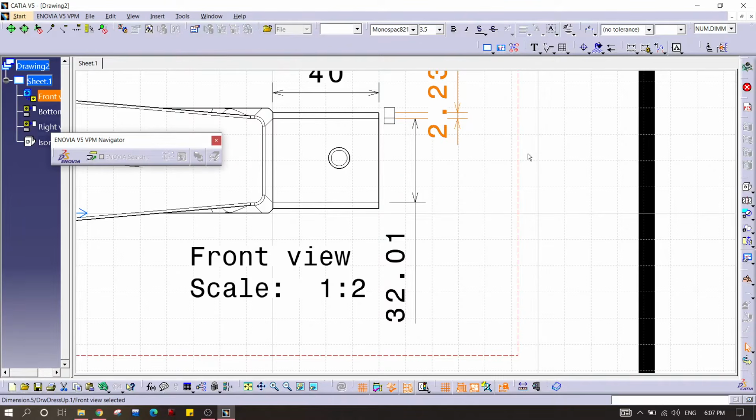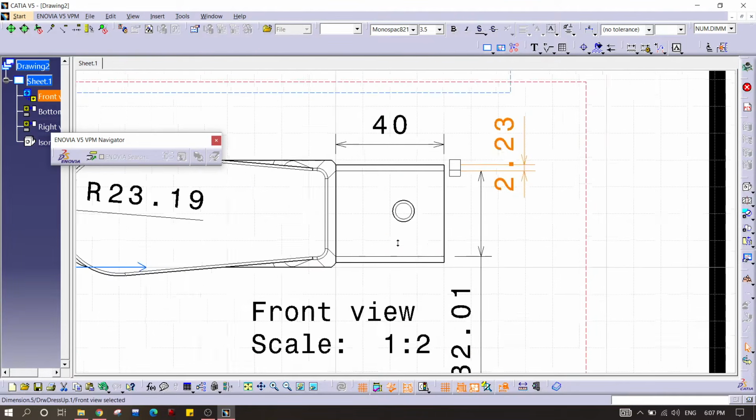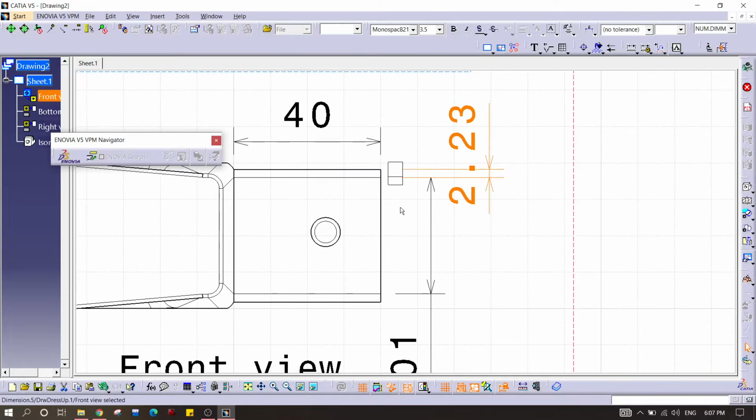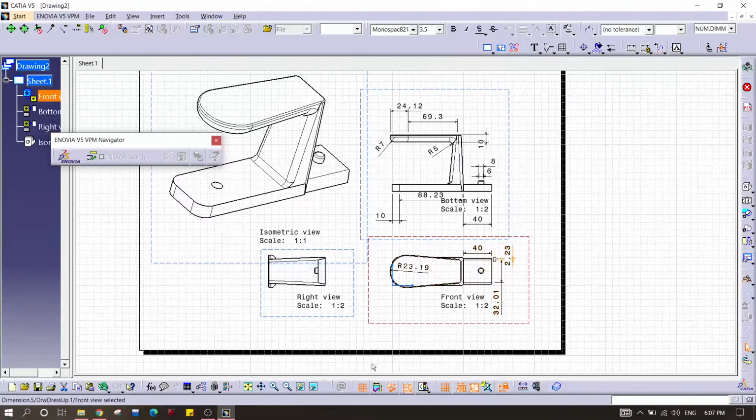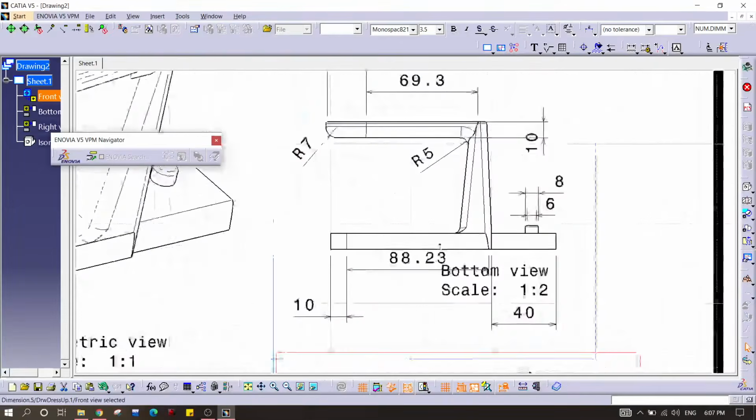It's 36 in length in total. Okay. Why are we getting this kind of thing? Because I had applied here, let's say, edge fillet. So by this it became round and it doesn't come in the whole dimension. Okay, I think it's done.